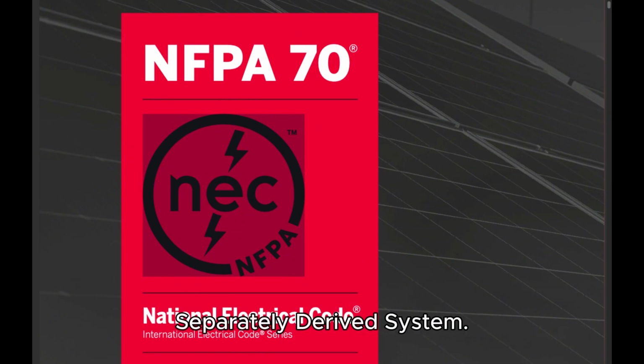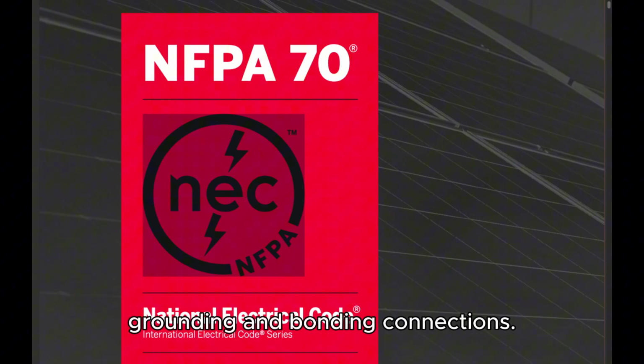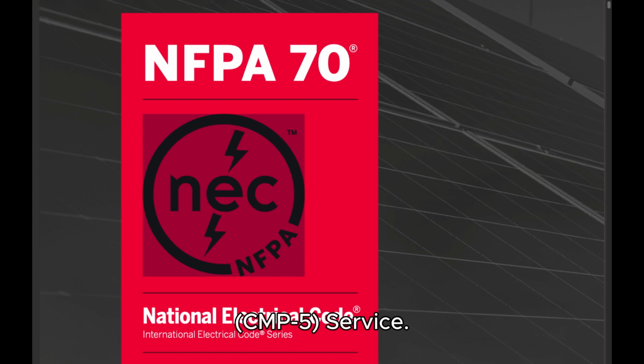Separately derived system. An electrical source, other than the service, having no direct connection(s) to circuit conductors of any other electrical source, other than those established by grounding and bonding connections. CMP5 Service. The conductors and equipment for delivering electric energy from the serving utility to the wiring system of the premises served. CMP4 Service cable. Service conductors made up in the form of a cable. CMP4 Service conductors. The conductors from the service point to the service disconnecting means.